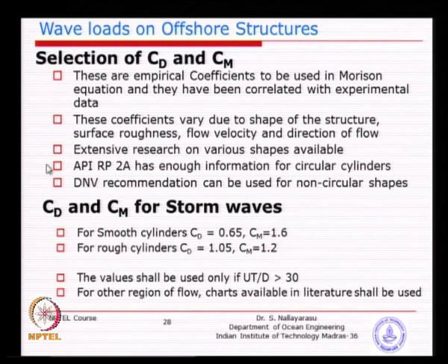And you can also use DNV codes, because API does not talk about non-circular sections, they always focus on tubular sections. So, I have just summarized in the next few slides recommendations given by DNV for various non-circular shapes, which could be potentially useful.